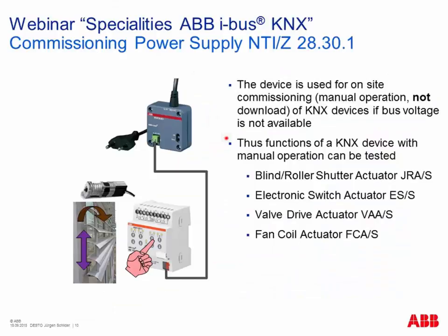We have another power supply, but don't mix it up. It's not a classical KNX power supply. It's only a simple power supply to connect to one KNX device only, to manually operate a component if it's available here. For example, if there's no KNX power supply available at the moment, but you would like to check the manual operation and the load behind, you can use this component here.